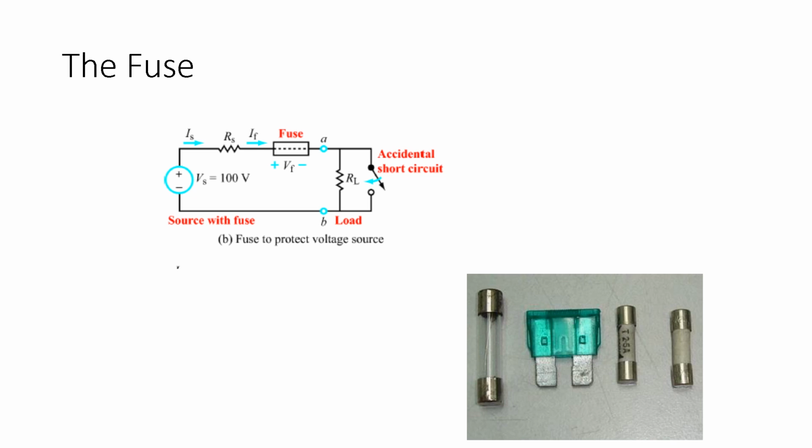And then three, because you've cut out the resistive element, most likely, as long as water's gotten the full way inside of there, and there's some kind of ions in the water to make it conductive, you're going to essentially damage some of the electronics in there, especially if there's any chips or whatnot, because those could be short-circuited because the water can go directly from the source all the way to ground. So if they're newer hair dryers with digital components in them, they can be broken as well.